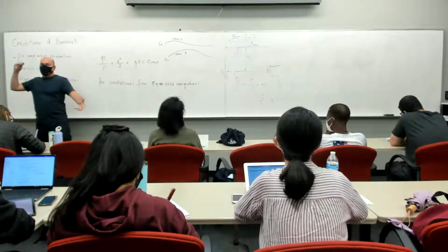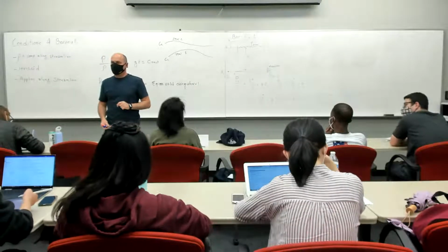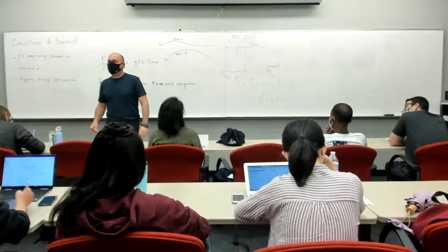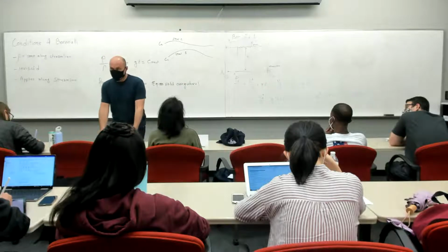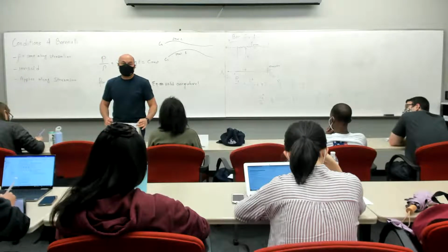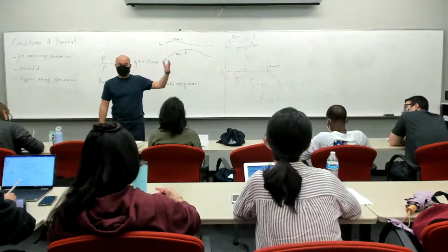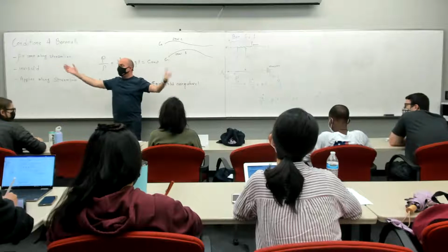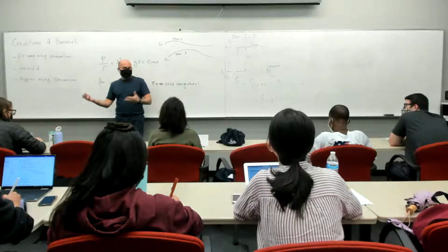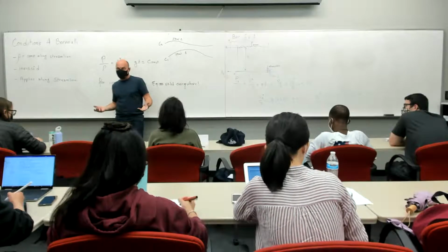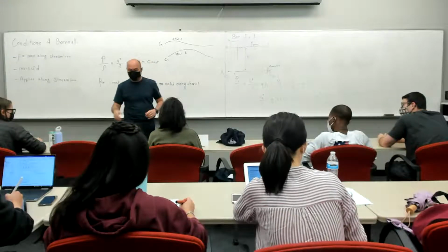You have a little tank, a little bucket, and you want to get an idea of what the velocity is. If the height of the bucket is h, then that's the velocity. Pretty nice. So remember the Bernoulli equation is a momentum balance. For mass conservation, we have the continuity equation. We applied it in the integral form. We know the differential form. Bernoulli is like an integral version of the Euler equation. The integration though is along a streamline, but it's a momentum equation. Think of it this way.